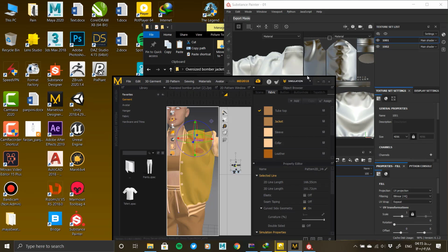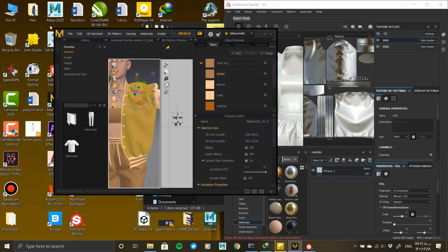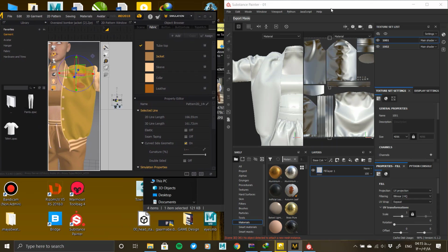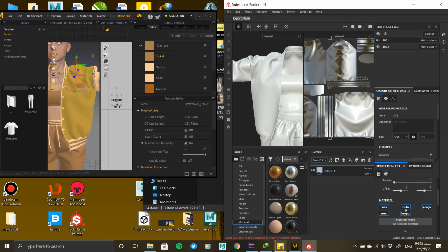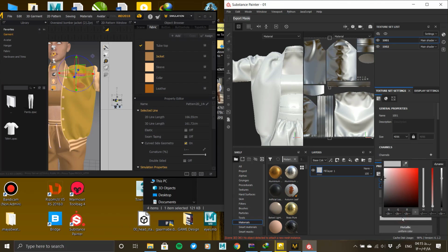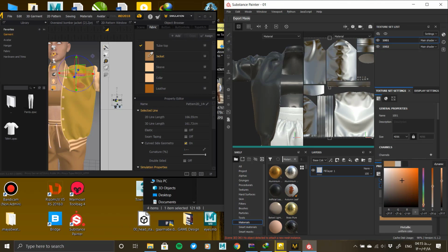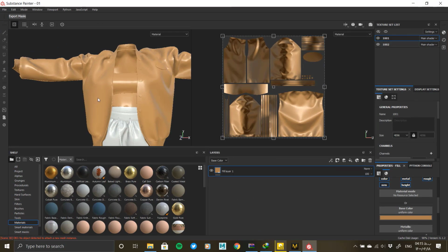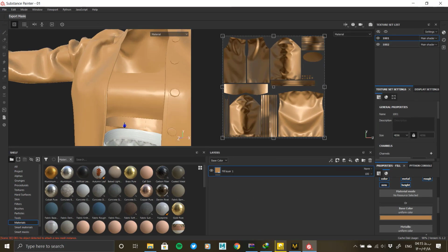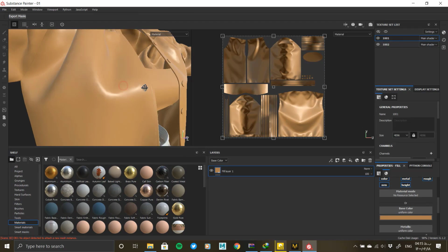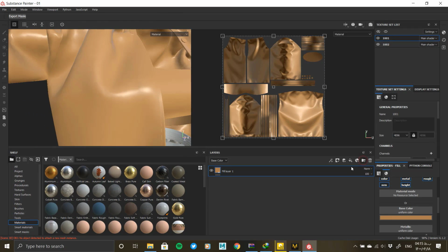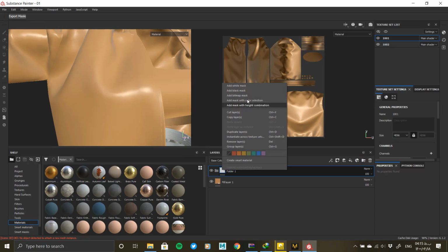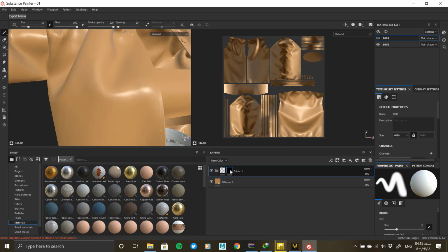The warp filter is used to create disorder and imbalance in the environment. This filter can be used, so that the material is not homogeneous. Other filters such as blur, sharpness, bevel, etc. can also be used, and by combining these, we can achieve the desired material. To add clearer noises and irregularities in the material, and add fine and messy details, it is better to use noise textures or grunge and adjust them manually.